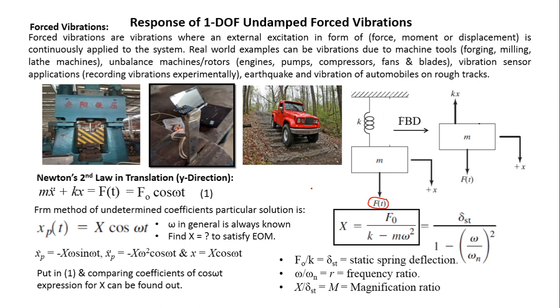So forced vibrations are vibrations where an external excitation in the form of maybe force, torque, moment, or displacement is continuously applied to the system. And there can be many real world examples of forced vibration. For example, the continuous motion of this forging machine tool, and for example the measurement of the vibration